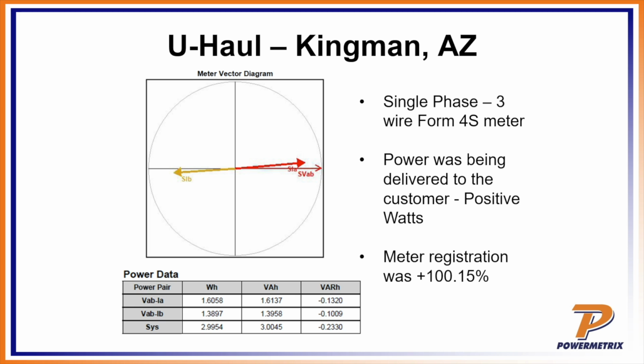We went and retested the meter. It is important to test the meter going in both directions so that you know you're getting good registration. We got plus 100.15%, and so basically we've checked the meter in both directions, and so that's a good thing, just to make sure it's doing its job.